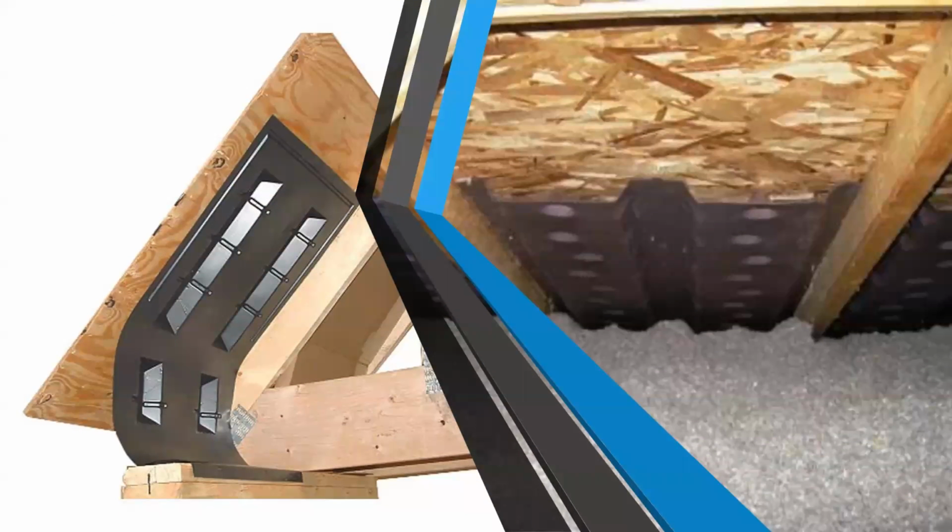So in the attics, baffles need to be installed to uphold the R value of the blown attic insulation. Correctly installing these baffles means it needs to be fully filling the cavity, as you see in the photo on the right, fully filling the cavity from rafter to rafter, not just partly in the middle. That's the correct position for that baffle to be installed. And on the left, you see another correct position of it being installed on the top plate. As you see, it's stapled on the very back side of that top plate, which will ensure that the top plates are covered with insulation and not exposed to unconditioned attic air.